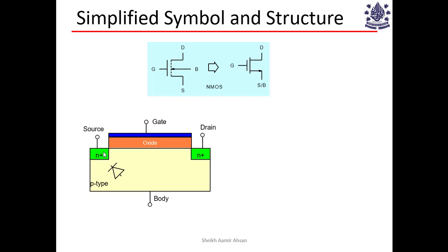We want them to be of absolutely low resistance, because when we put metals on top of these heavily doped regions, they usually lead to a very small amount of voltage drop, and most of the applied drain to source voltage is felt across the channel. That is the basic idea. You do not want that voltage to be wasted in these contacts. And also you have these PN junctions between the source, drain and the body, right?